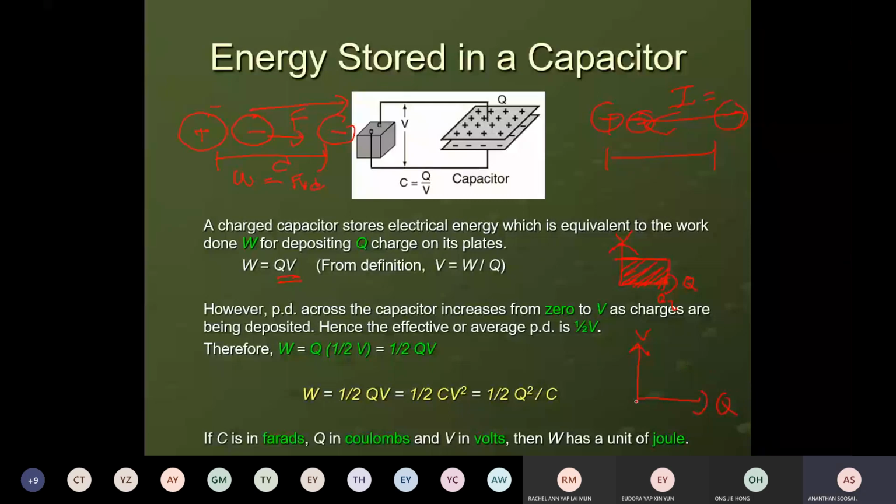When charge is stored, the voltage of the capacitor rises, linearly, because C equals Q over V, and capacitance is constant. So the gradient, Q over V or V over Q, must be constant. So it must be a straight line with a constant gradient.